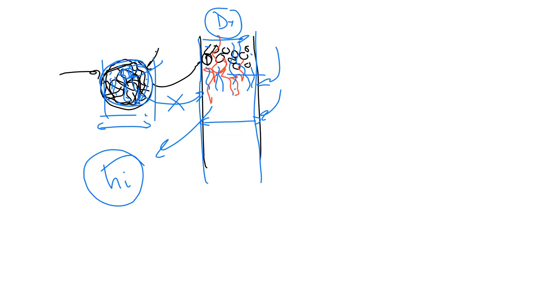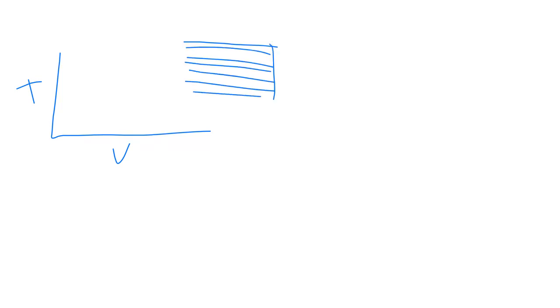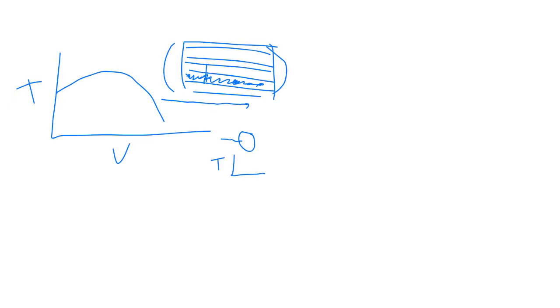And so you are absolutely right. It makes small little tubes for the reactants to flow through. What we are going to assume is a homogeneous temperature profile. What that means is, if I model the temperature over the volume of my reactor, with the whole thing with the tubes, as I flow through the reactor, we assume that in my tubes and also in the catalyst particles, at different positions in the tubes, there is no profile over the catalyst particles themselves. So I don't have a temperature profile over the particle, if you understand what I'm saying.